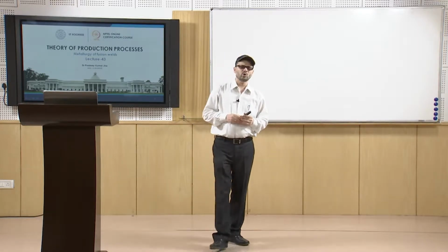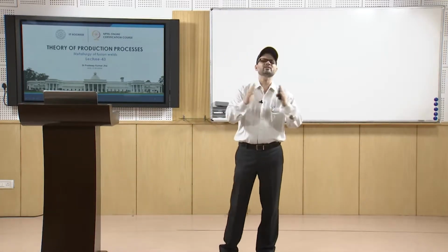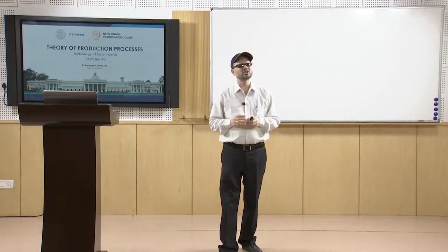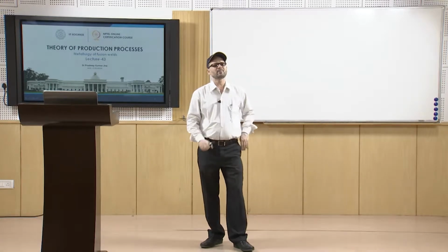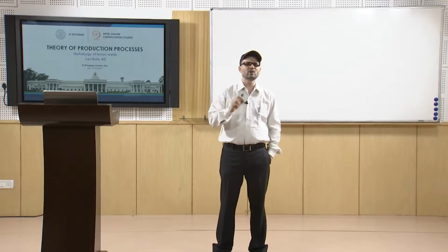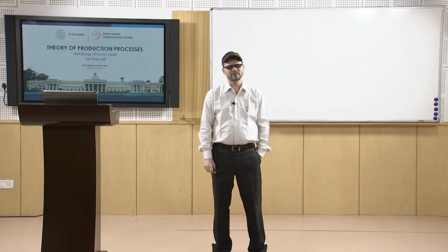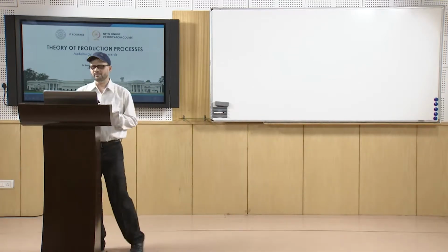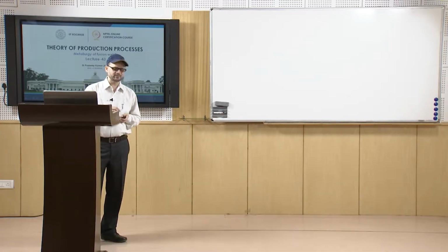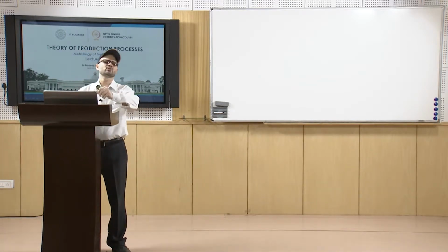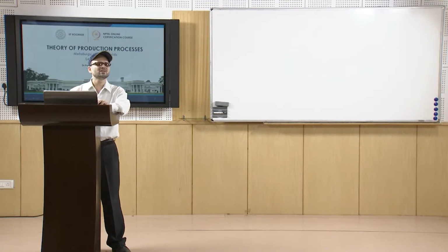How wide this zone is, and up to what distance its effect can be seen, depends upon the heat input per unit time, the welding velocity and the physical properties of the work material. The heat input per unit time may be more or less, and the welding velocity may be more or less.